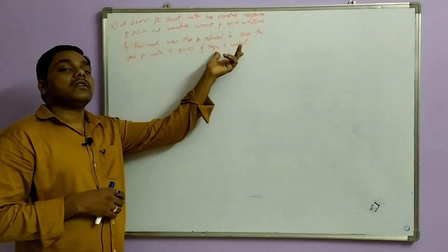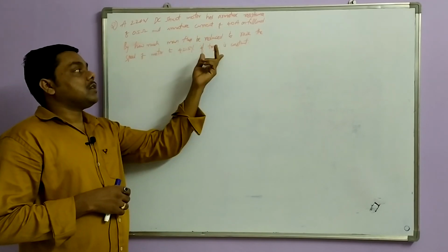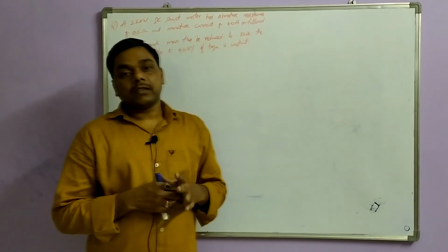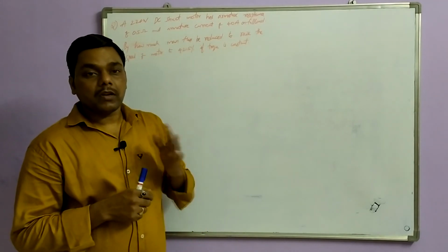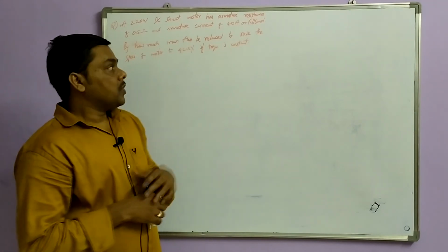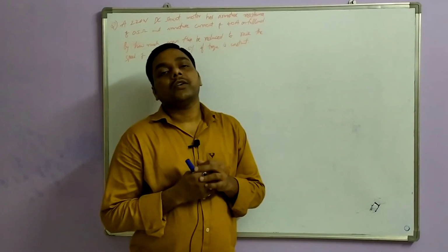Now the torque is constant. So when speed increases and torque is constant, there is an immediate change in the flux. Flux and speed both change, torque is constant, so armature current also changes. So we cannot directly calculate flux, but in terms of armature current we can calculate.